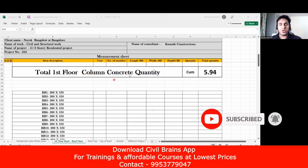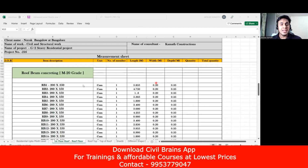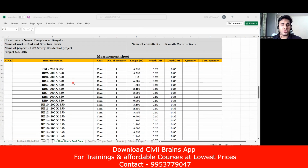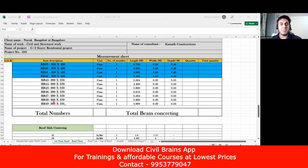Once we have found the concrete quantity, next we'll find the concrete quantity for the beams. Shuttering I'll do later. Now again, I've written here roof beam concrete quantity, and it is M20 grade of concrete. Again, I've written RB1, RB2, everything up to RB49. So you go back to the drawing.